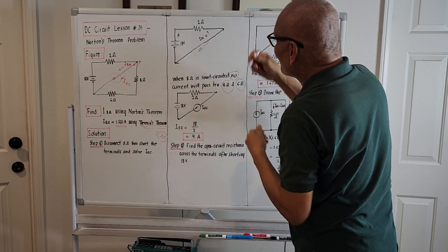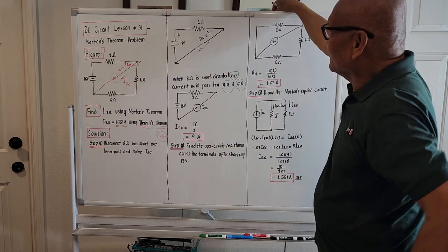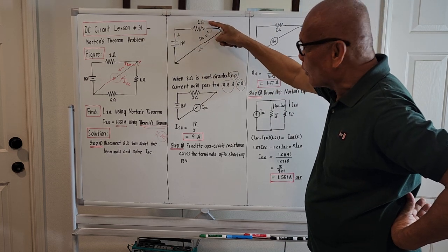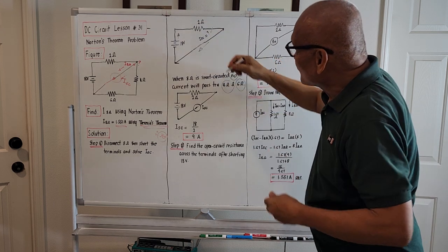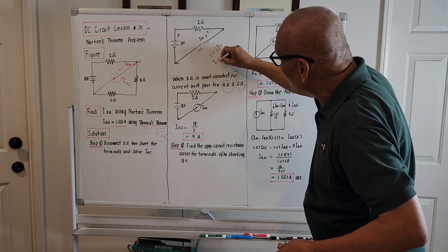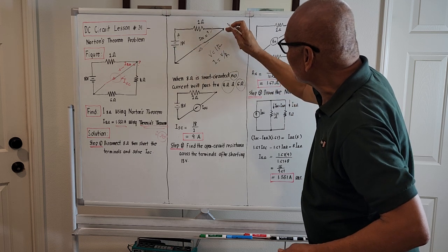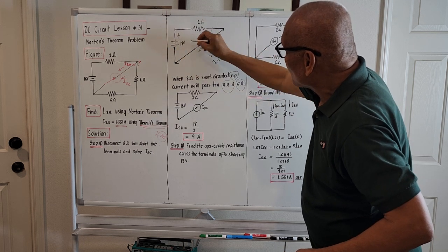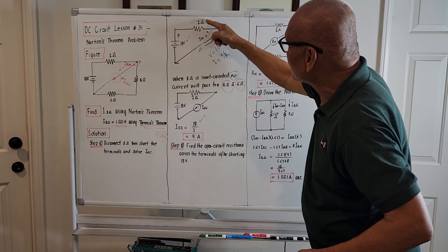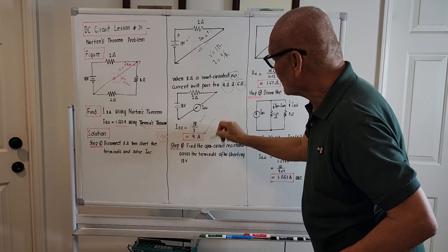Okay, so actually we could compute for the short circuit current now. If we try to visualize the circuit, it is just an 18 volt source connected in series with the 2 ohm load. So by using the equation voltage equal to IR, we could compute for the current. It will be voltage over R. For this resulting circuit, after the shorting of the terminals, the voltage will be 18, right? And the resistance will just be simply 2 ohms, this over 2. So what will come out for the short circuit current is 2 amperes.